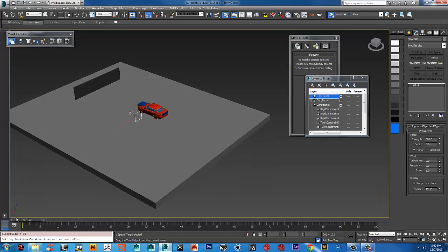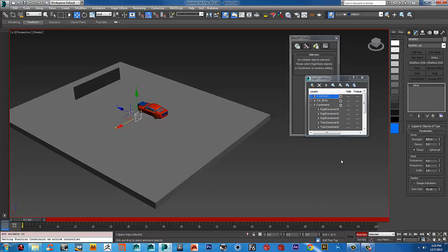So I want it to be animated. Let's check very quickly where I want it to be animated. Right. So I'm going to click N. I'm going to have 500, let's say until frame 25. Change it back to 500 here. And I'm going to move this one all the way up here and change this one to 0. So you've got 500. I'm going to delete that key. You've got a key for 500. Then after that, this key here, we need it to be 0, so the wind will stop.